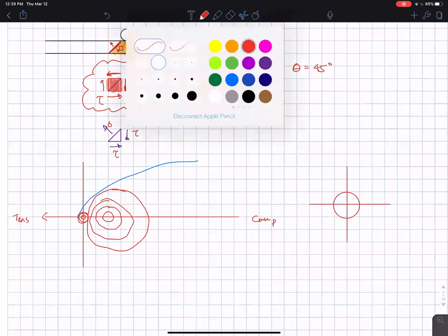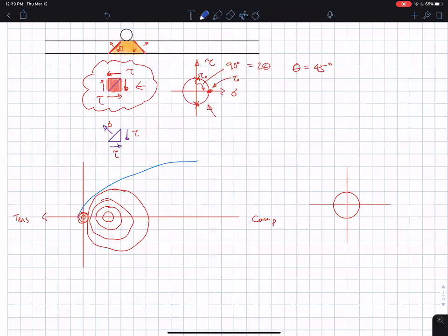And let me exaggerate, drawing the failure envelope. The blue line is like this. This here is the shear strength, and this is the tensile strength. Your Mohr circle will hit this tensile strength before it hits the allowable shear strength every single time. It's extremely difficult to purely shear concrete. We'll talk about a case where you can do that. But typically, you're going to fail in tension, and this tension happens along this diagonal.